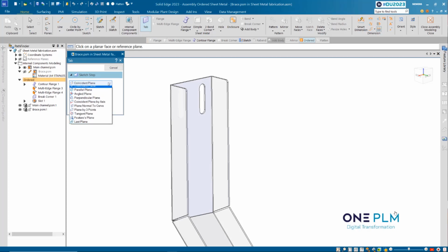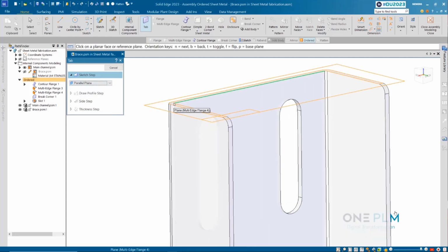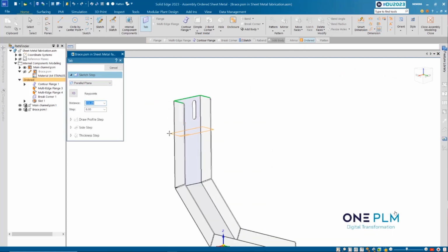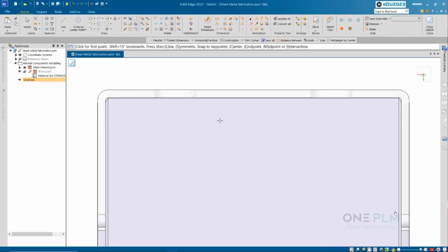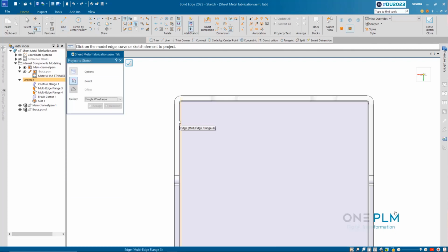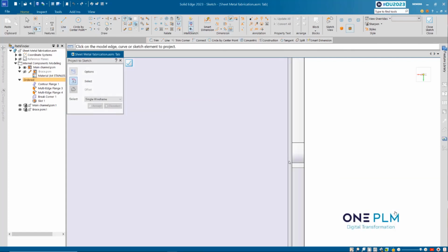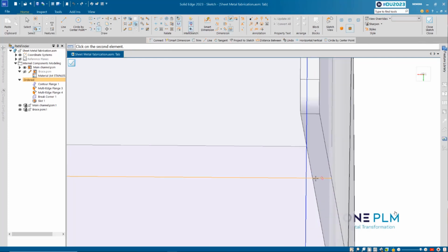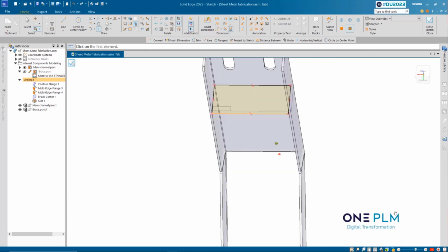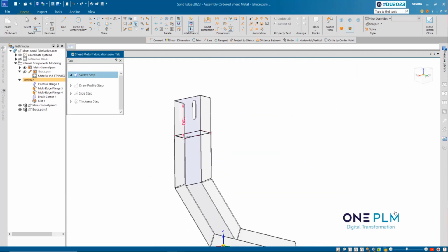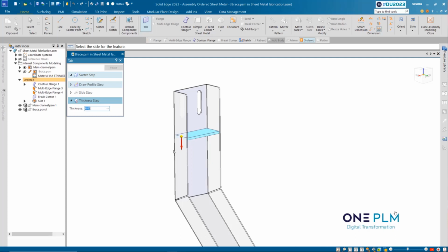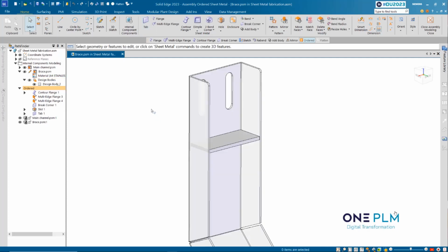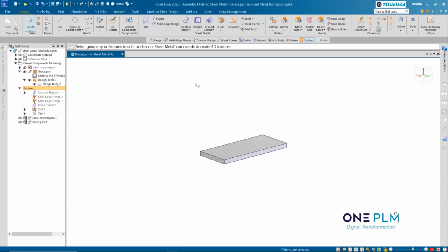Let's do a parallel plane because we want to drag this down from this top face. So what it's doing is creating associativity, but it's associativity within the same part, which is really nice. We haven't got to worry about linking items because everything is within that same assembly. I'm just going to spin that model around, and then use a trim command to make sure all this is trimmed up nicely. I keep that as simple as possible, but this time notice my thickness is going to be 6mm, which is twice as thick as the original material that we've got.